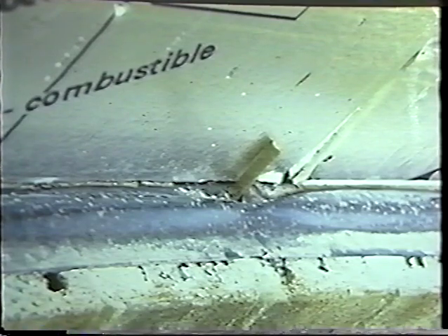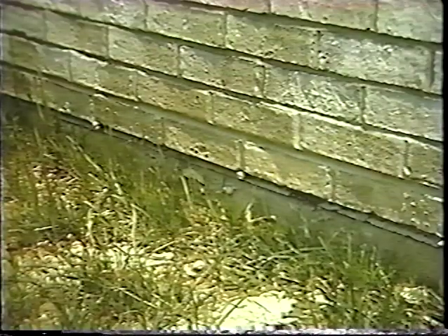Flashing should be placed behind the sheathing or sheathing membrane. It should run under the brick to the face of the wall to form a drip edge if possible. Don't stop the flashing back from the face of the wall. Flashing that is held back from the face allows water to bypass the flashing and re-enter the wall and house. Flashing can be installed with the edge protruding from the wall and then cut flush when the wall is complete.